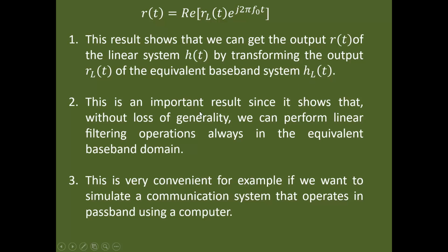So this is an important result since it shows that without loss of generality, we can always perform linear filtering operations in the equivalent baseband domain rather than in the bandpass system. The reason I have already explained: for doing the operations in the bandpass system, you require complex electronics hardware, and the cost of the systems will also increase. So this is very convenient.